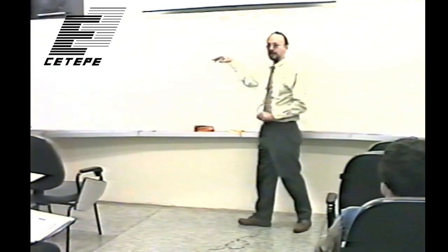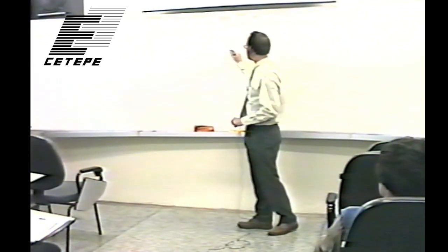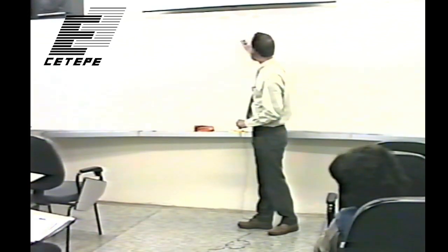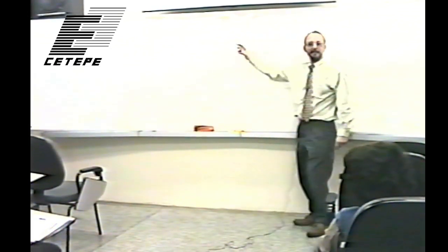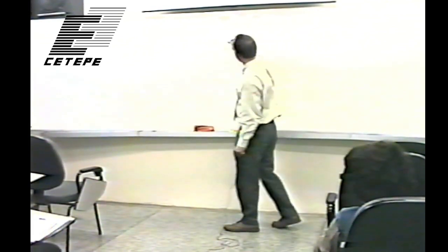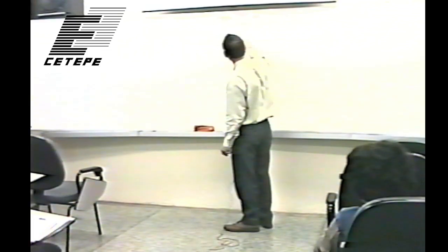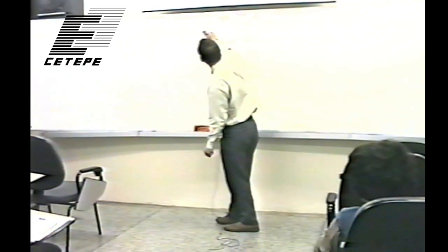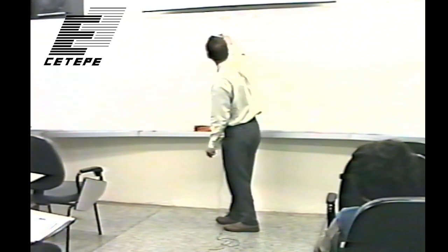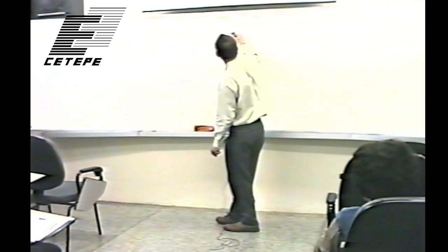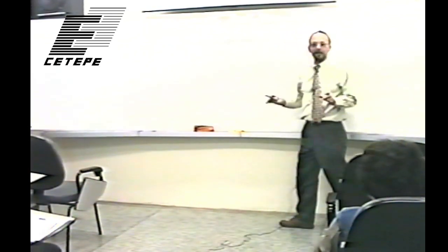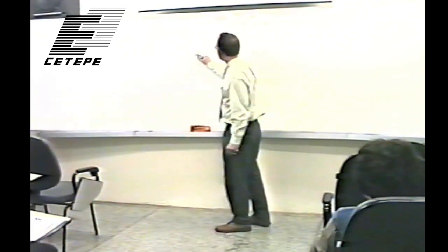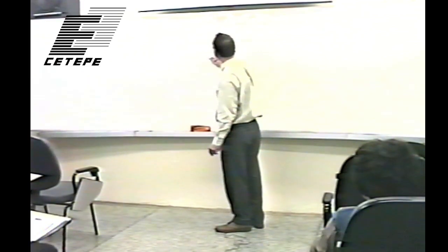electrodes on the surface of the silicon. So you have, this is the bulk silicon down here, and there's usually a silicon oxide. Whatever silicon oxide is, there's an insulating layer on the top. And then you have this repetitive pattern of what's called gates, or electrodes. And they're often referred to as Phi1, Phi2, and Phi3. And then it would repeat, Phi1. It's always in a 3-phase device, which is the most popular. Each pixel has 3 gates over it. So a pixel would go from here to here.